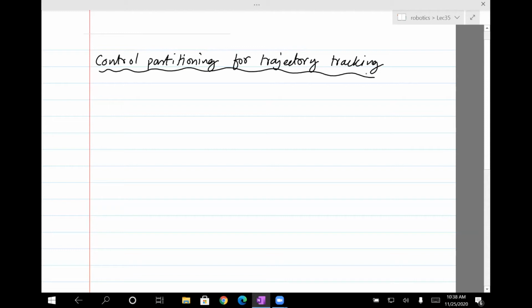So what we did so far was I showed you how to get the pendulum to go from 0 to 90 degrees in one shot, right? But that's not what you want to do, because that just makes the system very jerky. Imagine going from 0 to 90 degrees in 0.5 seconds. That's not what you want. What you want to do perhaps is to get the system to go from, let's say, 0 to pi divided by 2, which is here, in say 3 seconds.